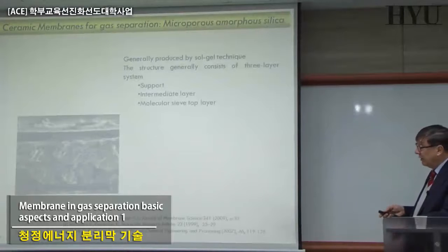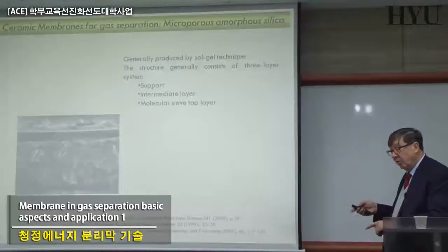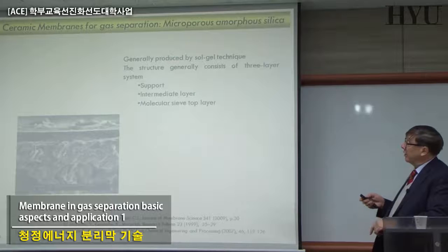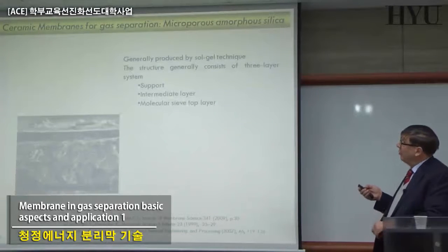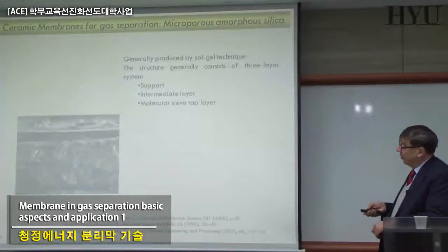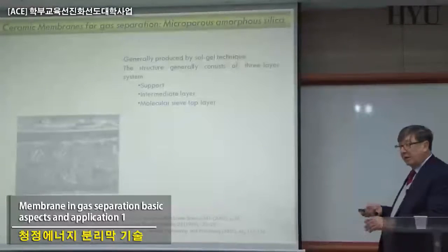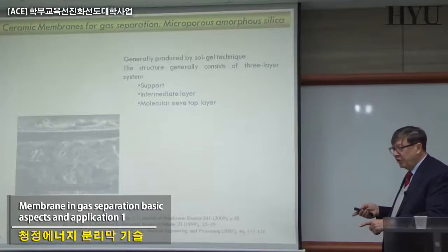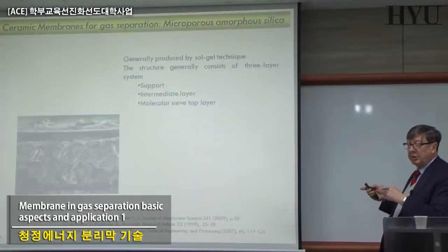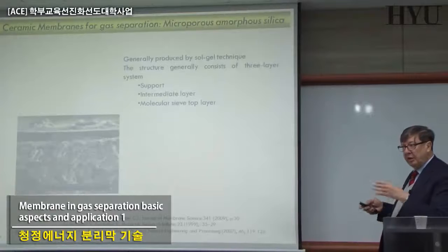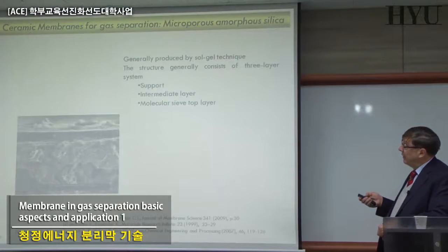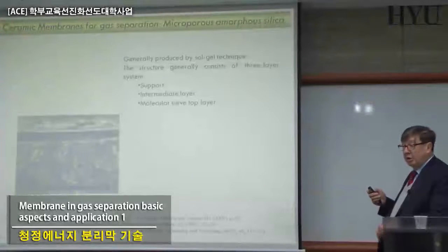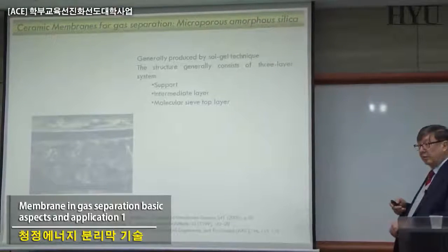As we discussed already, not only polymeric material can be utilized for making gas separation, but also, in the case of gas phase, we can have inorganic ceramic membranes. Eventually, the mechanism will no longer be solubility-diffusivity, the one that we have been describing for most of the polymeric membranes that we are utilizing, but you can have Knudsen diffusion or viscous diffusion,